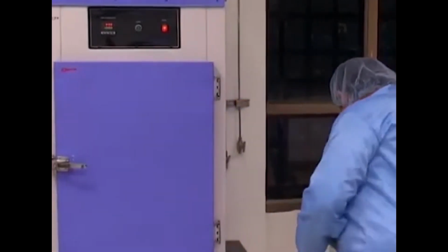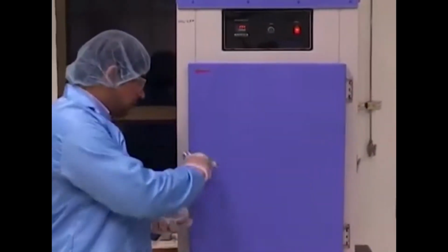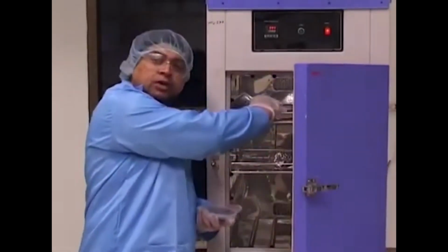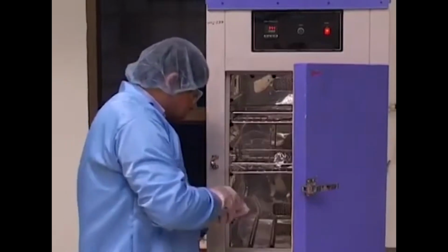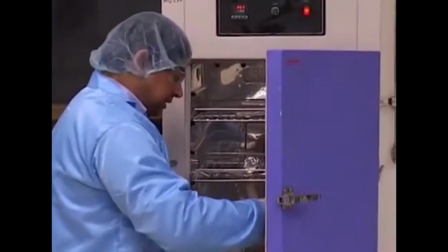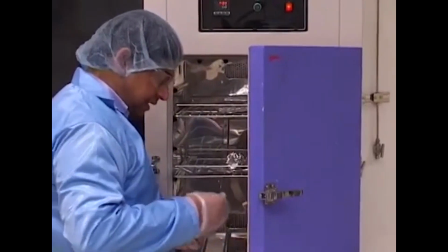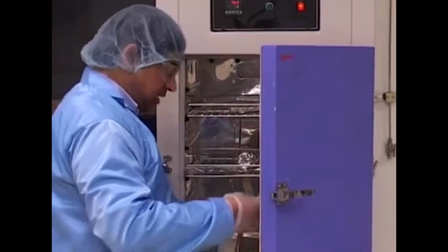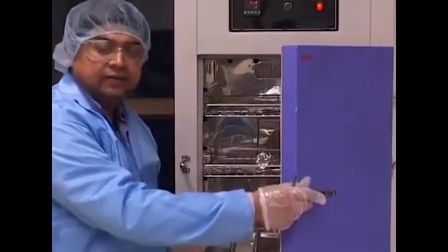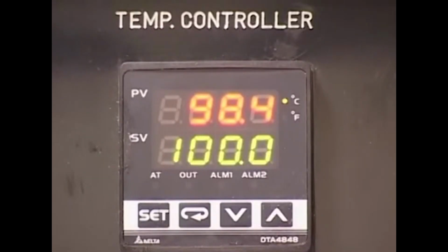So what we basically do is take the wafer box which we pulled out of the fume hood after the Piranha clean, put an aluminum foil on the top of one of these shelves, and then slowly load our wafer sample so that we can get it heated and remove any water if present on the surface of this wafer. The whole idea is to have a perfectly dehydrated surface of this wafer, so that it can be good for adhering to the photoresist that we spin coat on the top of it before doing photolithography.